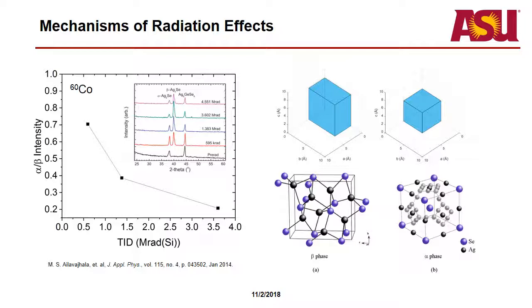And then there was one study that actually found that the transition temperature from beta to alpha actually depended on the crystal size. So for nanocrystals, the transition can actually happen at 101 centigrade. And so even then, though, like most of these tests, these are performed in room temperature. And so the fact that these alpha phases even exist are really surprising, but it makes sense when you consider that the germanium also in this material is helping to confine those nanocrystals, put pressure on them to allow them to exist at this higher temperature phase.